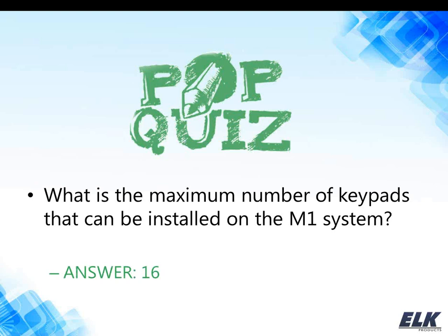This number 16 refers to type 1 devices, which include keypads, access modules, and supervised power supplies. So if you are going to be using access modules and/or the supervised power supplies, keep in mind that that total number of 16 includes those devices as well.